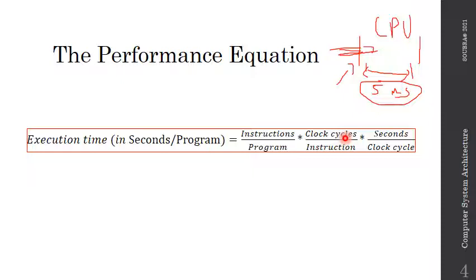So basically, if I implement it in a way that it will take many clock cycles to execute an instruction, right, the hardware implementation of it means that my execution time will be slower. And if I implement it using different techniques, one of which I'm covering in this part of the course, it feels like we can reduce the number of clock cycles needed to execute an instruction.